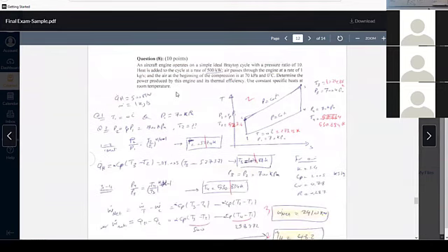This is the Brayton cycle. It's an aircraft engine, the Brayton cycle. The pressure ratio is so important, P2 over P1. I like the TS diagram. Compression, heat addition, expansion, heat rejection. Compression from 1 to 2. Heat addition from 2 to 3. Expansion in the turbine, and the pressure lines are diverging. You need to make it a little bit more diverging than I did. And 4 to 1 heat rejection. Again, isentropic compression, constant pressure heat addition, isentropic expansion, constant pressure heat rejection.